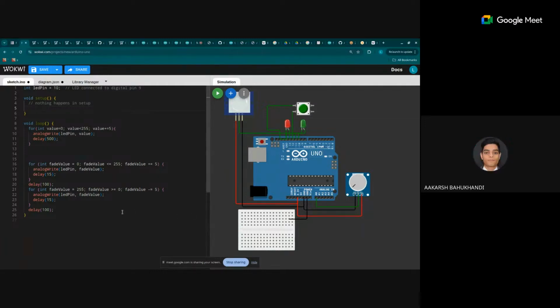Sir, if we connect the breadboard to the ground, then the breadboard would act like a ground. Yes, that particular row, not all of it. I think this one column is connected. In this orientation, it looks like the column will have the same voltage. So each column will have the same voltage, which means if you connect this here, this will also be ground. That's how it works in breadboards.